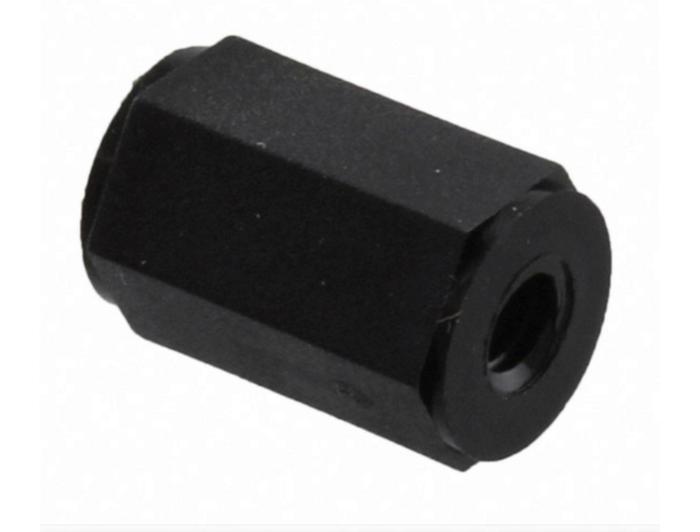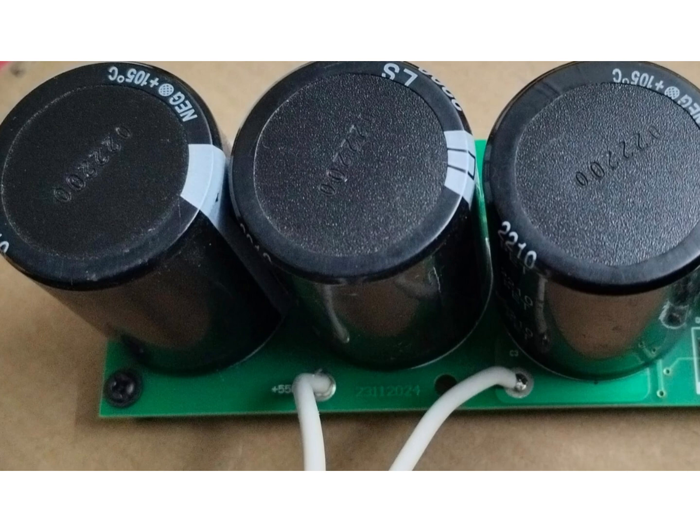sections of the inverter. On this board, bulk DC-link decoupling capacitors are not placed directly on the PCB. Instead, the design assumes the use of an external electrolytic capacitor bank connected across the HV+ and HV- terminals. This approach allows the bulk capacitance to be sized according to the application requirements, such as power level, load type, and ripple current rating, without increasing PCB size or cost.